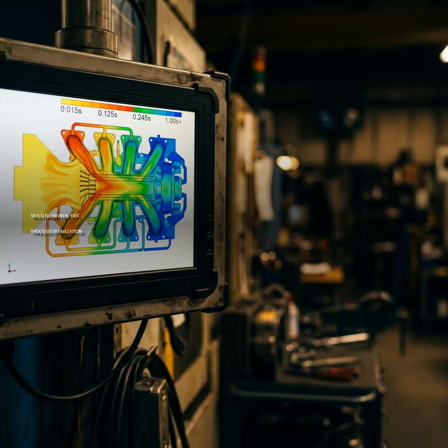You mentioned clamping tonnage earlier. Is there a specific output for that? Yeah, there's usually an XY plot of the clamping force. This shows how it varies over time, influenced by filling, holding pressure, and VP switchover. The big thing here is ensuring that the maximum clamping force doesn't exceed what your injection molding machine can handle. Exceed that, and you're looking at potential equipment damage or bad parts.